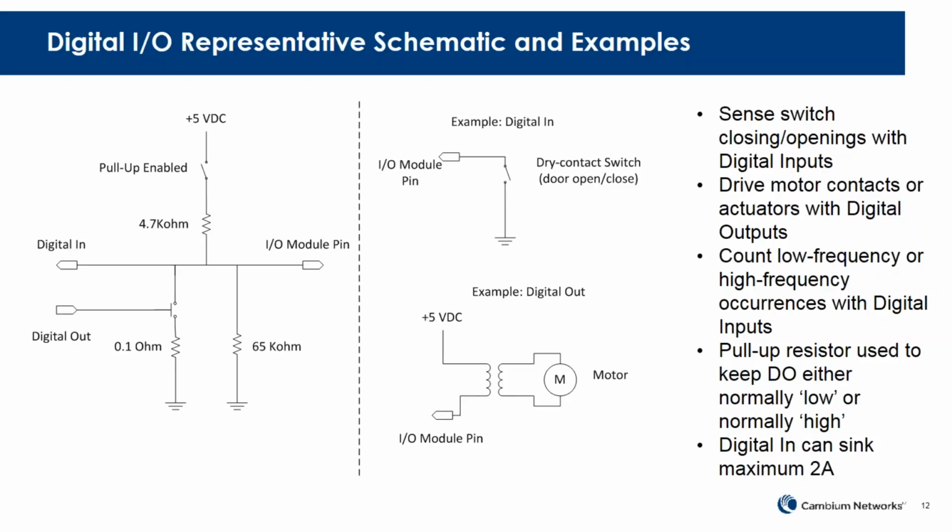And those go into our system on that I/O module pin. They go through that circuitry, and then you'll see that digital in and digital out on the left. And that's what the programmers are going to do when they look at an IIoT application. They're going to read inputs and write outputs, all the way back from the cloud, and it's going to take that physical action on the schematic or on those sensors or actuators.